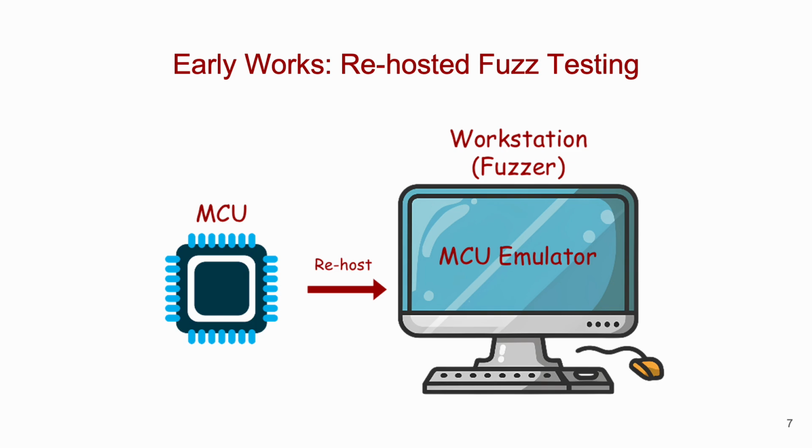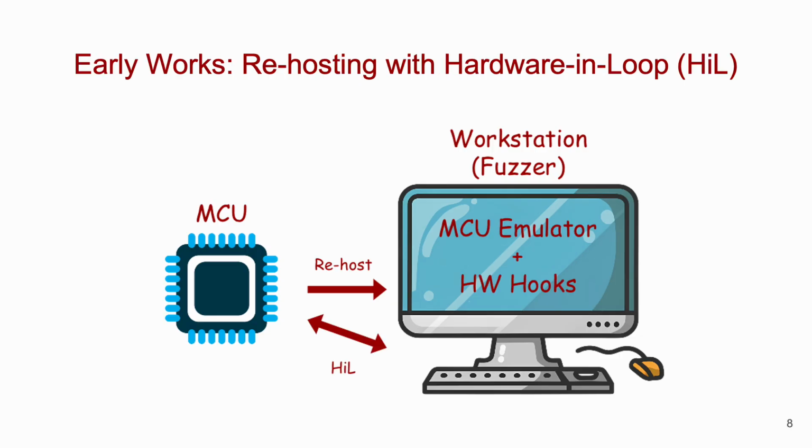To solve this challenge, early works proposed rehosting the embedded application on a more powerful desktop. In this setting, the microcontroller hardware is emulated on the workstation through sophisticated techniques. As such, both the fuzzing and execution of the target binary happens on the desktop device.